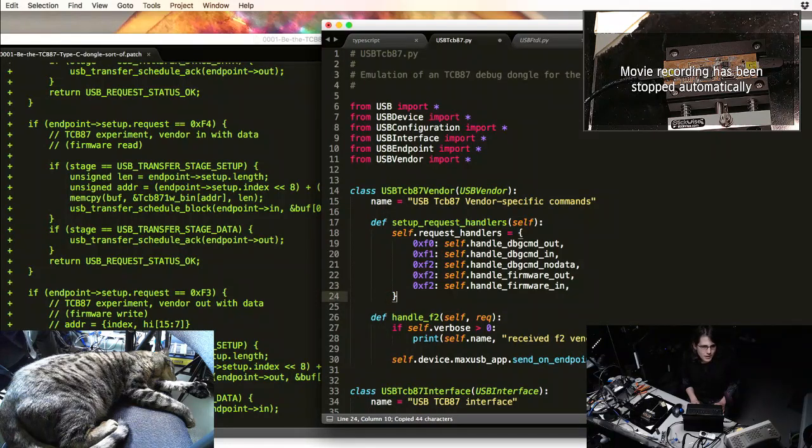Logically, it's like we have a bunch of separate ports here, almost like different endpoints, but logically separate from the endpoint system. A lot of the time, if you had different logical bits of functionality inside a specification or some firmware, you might do something like this, where you allocate an entire vendor request number and then do some more command multiplexing inside that.